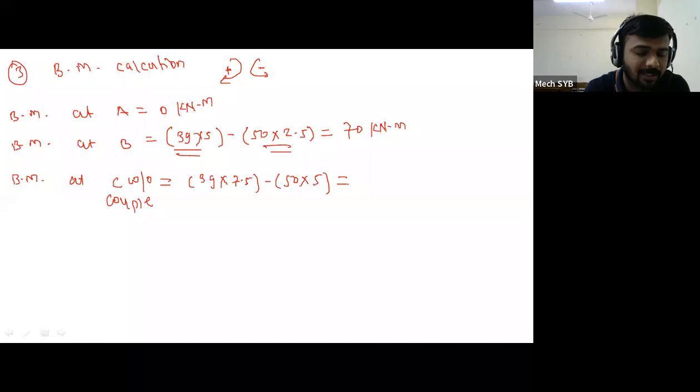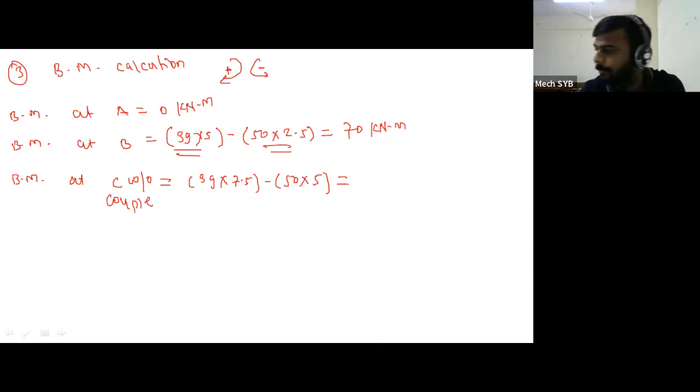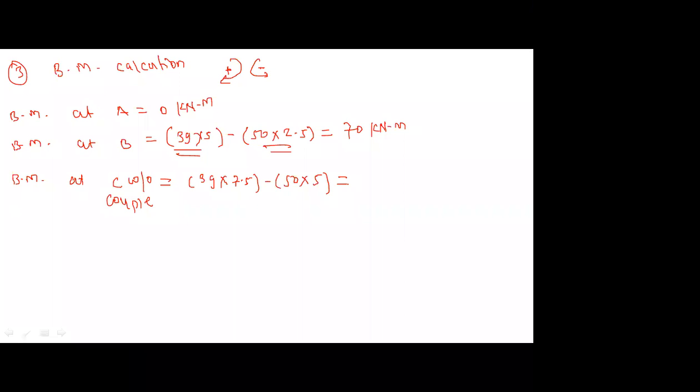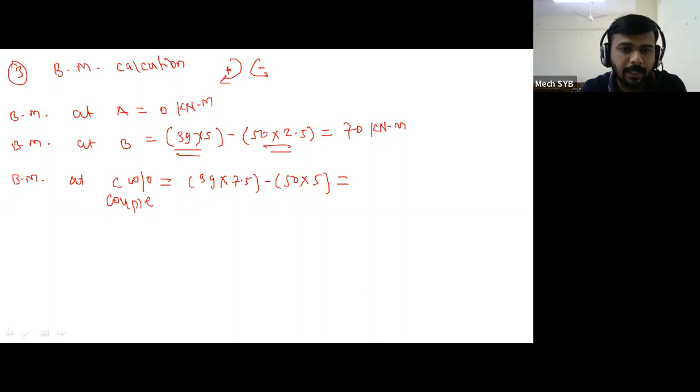जसं रिएक्शन कॅल्क्युलेशन करताना जसं SF कॅल्क्युलेट करताना आपण जर एखाद्या पॉइंटवर जर पॉइंट लोड असेल किंवा रिएक्शन असेल तर त्या ठिकाणी विदाउट लोड आणि विथ लोड कन्सिडर करतोय, पण कपलचा इफेक्ट आपण SF मध्ये कन्सिडर करत नाही. But while considering the effect of couple in BM calculation, take without couple and with couple condition. So write down in your notebook. Take without couple and with couple condition during BM calculation.